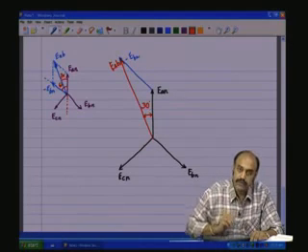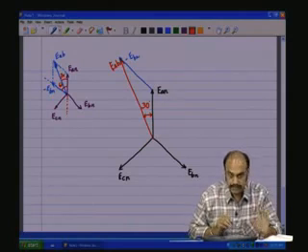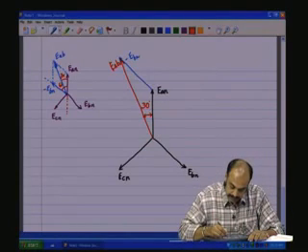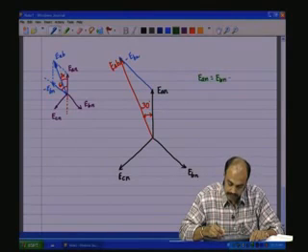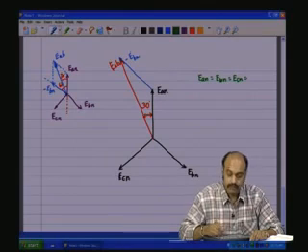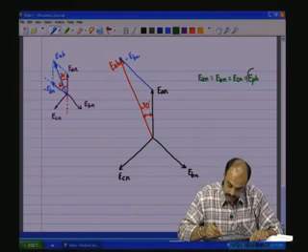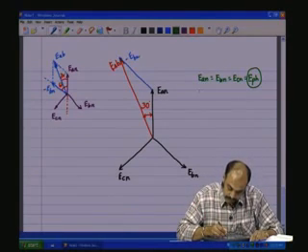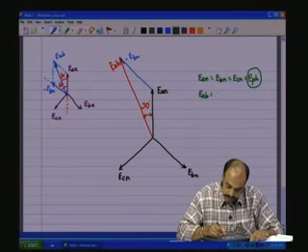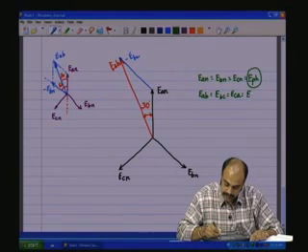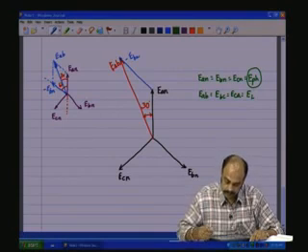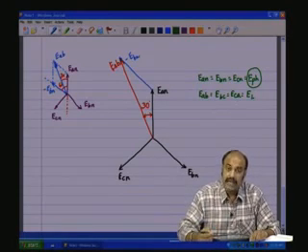Now, we said that the amplitudes of all the phase voltages effective values are the same. So, therefore, let us say EAN amplitude is equal to EBN amplitude is equal to ECN amplitude, which we shall call E phase. Likewise, EAB amplitude will be equal to EBC amplitude will be equal to ECA amplitude. We will call this one E line. So, that is the EL is the line voltage.